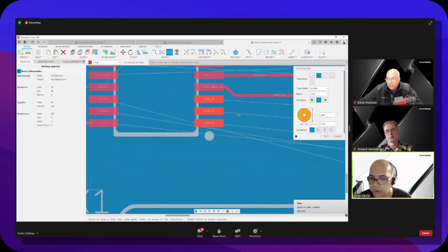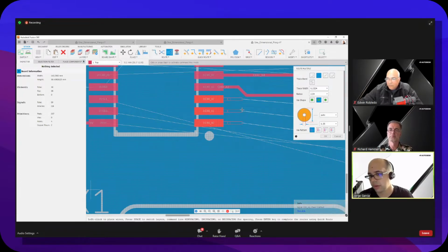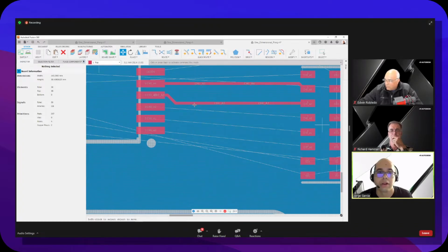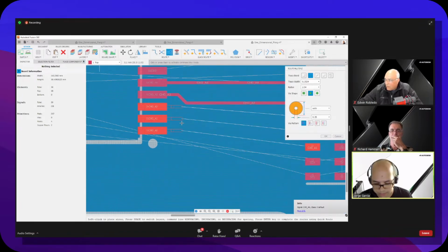Okay, I will go ahead and right click to begin routing. And you'll see, again, they can all push. Now, the spacing between them is actually controllable. So you have the M key for minimum spacing. Oops, I closed something. Or I called the move command. So actually I did the wrong one. Happens to the best of us. Go ahead and do that again.